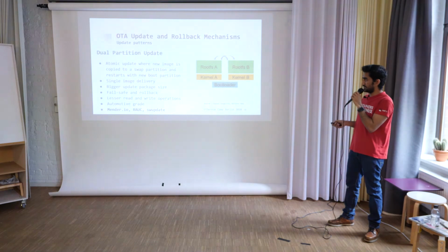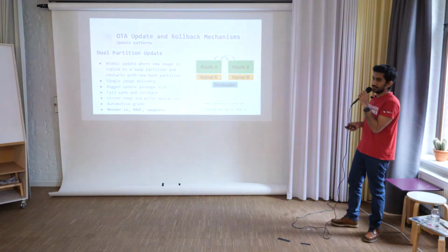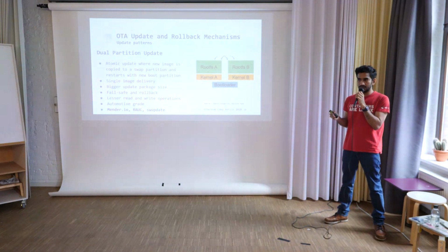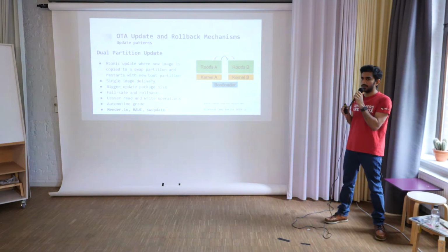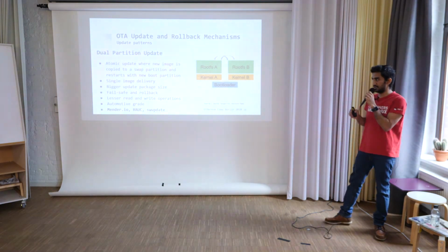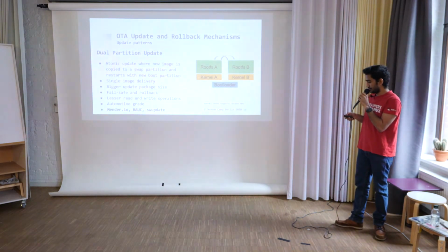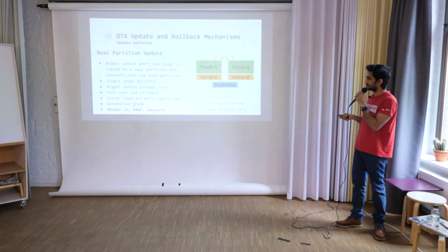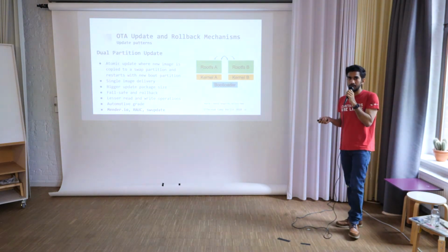The best one is this dual partition update. Every time, you update the whole image, and if everything goes well, it's an atomic update. You just flip in the bootloader to go to the new boot partition. In this way, you can make sure that the whole image, even your dependencies and your root file system, everything is updated. The problem is that it's usually a big package.